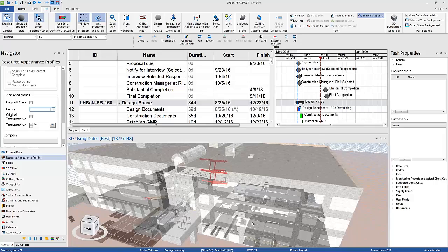So we built a 4D schedule for the structural scaffolding, and we used that as a way of figuring out the constraints of the area. We also built that scaffolding as a 4D sequence because it was inside of a mall, to explain to all of the retail tenants where the scaffolding would be at any period in time, so they knew how it would affect them as a tenant. It's very valuable. Yeah, terrific.